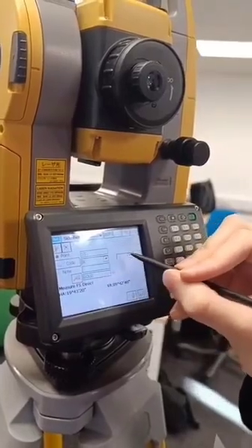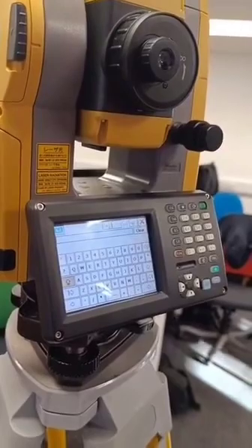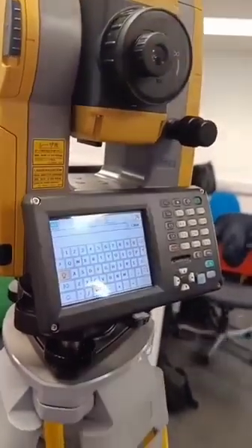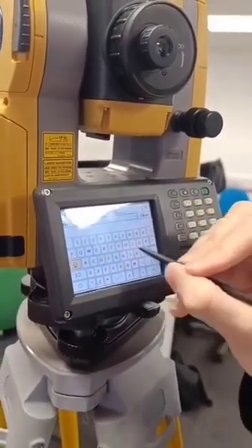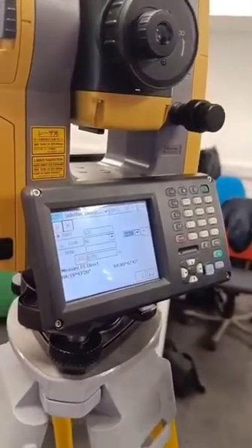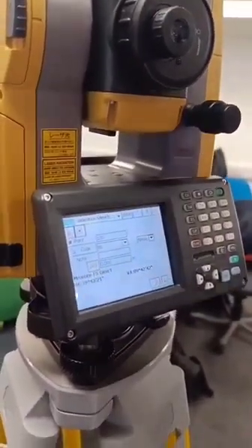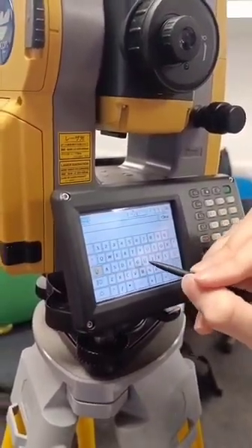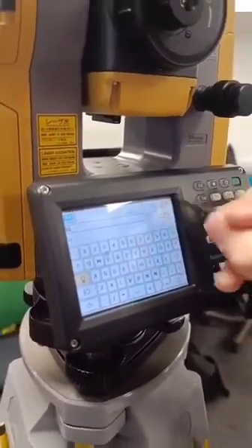So I'm going to go on building line, and I'm going to tell it that this is building line. If I want to go detailed, I can tell it it's the north wall, for example. I don't know if that is north, but I'm just going N wall. Just to tell the machine that this is the north wall, that one there that I'm measuring. And I'm going to change this from line point to rectangle. And in the notes, I can add a bit extra. So I'm going to do the bottom left corner first. So I can put just an abbreviation, BL, or bottom left if you want. And in your notes on here, I would write the same, just to keep track of what you're recording.